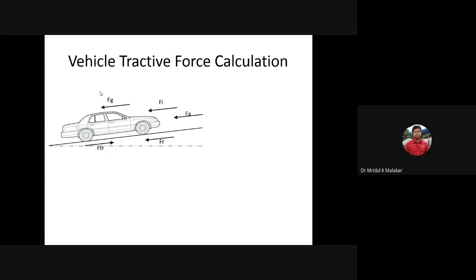Why am I saying this? Because before applying any control system or embedded system design, we need a full understanding of the system. So this is one system, and the total force, FTR, is the total tractive force. That equivalent force I have to apply, so I need to know which forces act here. One is the rolling friction: from the road profile and the tire friction comes the rolling force. Another is the air drag, the aerodynamic force.